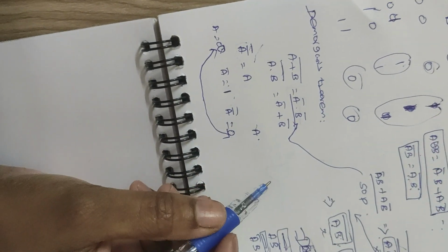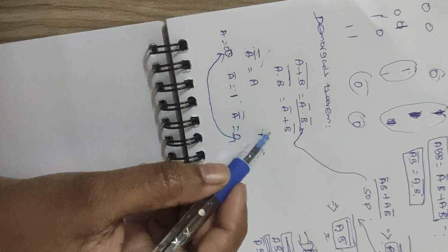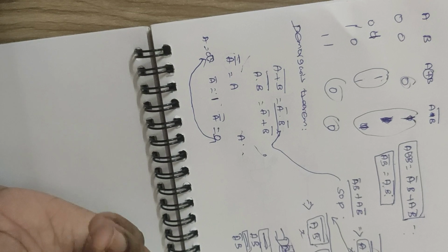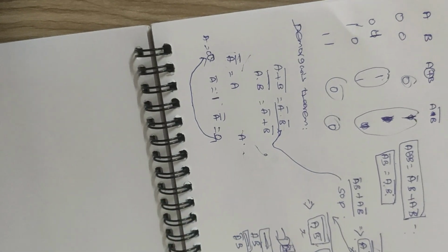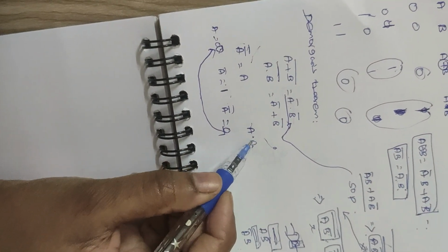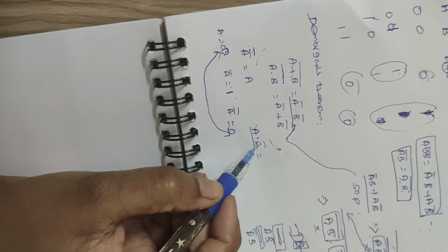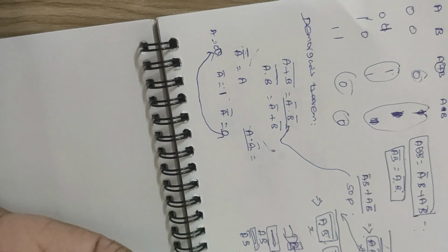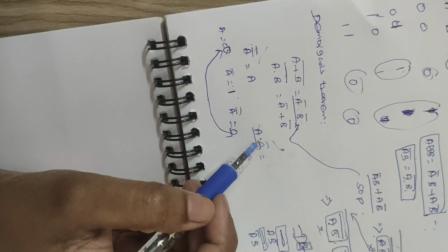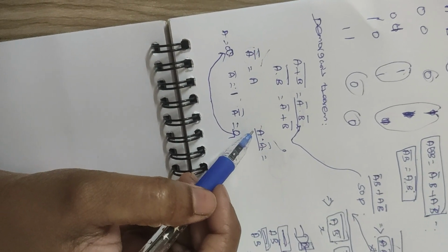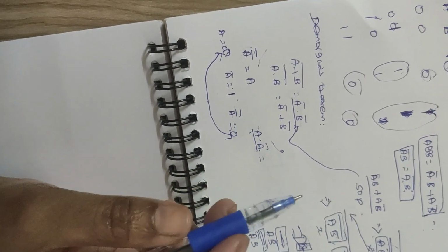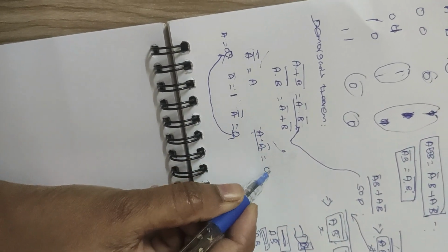So consider I have one input as 0, and generally AND gate operation we know, right? If any one of the input is 0, my AND gate output will be 0. That is the general definition of AND gate. So what I am trying to tell, A and A bar. Okay, in binary how many bits do we have? Only zeros and ones. So definitely if A bar is 0, then A will be 1. If A is 0, A bar will be 1. Anyway, any one of these two will get a value of 0. So A dot A bar will be 0.